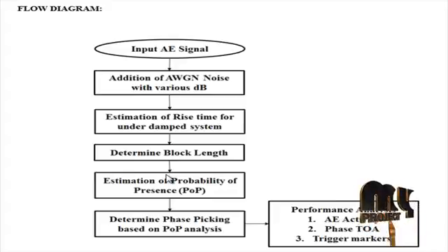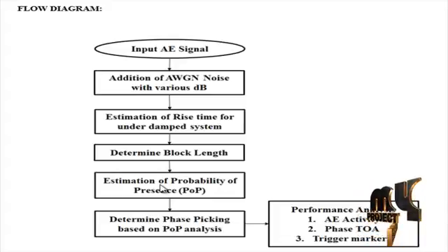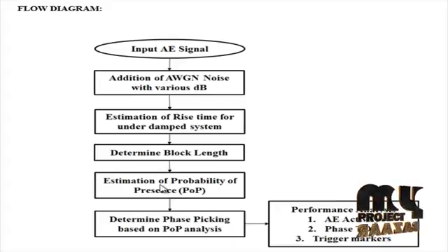Estimation of probability of presence. Signal presence probability is derived from the estimation of clean speech spectral coefficients in a signal enhancement task, using both a fixed a priori signal to noise ratio and a fixed a priori probability of speech presence. The proposed posterior signal presence probability estimate achieves probabilities close to 0 for signal absence and probabilities close to 1 for signal presence.